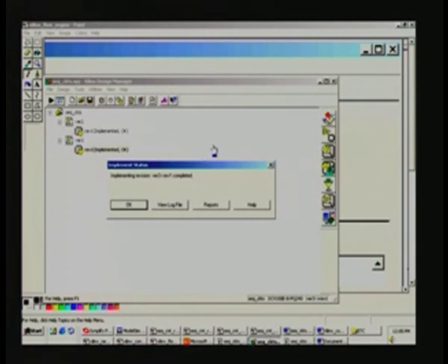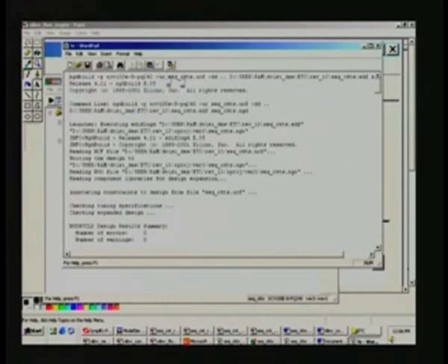What we have to say is we have lots of information available. There are report files here as well as a log file here. Whatever process was reported, you remember that it reported online in real time while the place and route was going on, it was continuing to report. So, all those reports will be compiled and available here, view log file. So, we can have a look at the view log file so that we can understand. So, this is the log file.